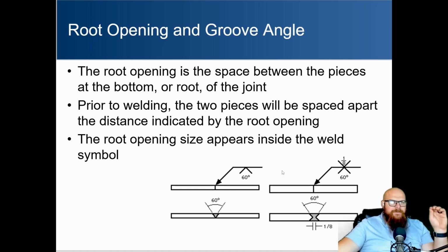So this example is a really basic example of a welding symbol, where you're going to have a butt joint, and underneath on the reference line, we have a double bevel. That means we are going to be creating a bevel on both pieces, and those bevels need to add up to a 60 degree angle. Now, even though it's underneath the reference line here, on the actual drawing, the top of that weld is where we're going to bevel. That's where we're going to make that joint. And then together those things are going to be a 60 degree angle.